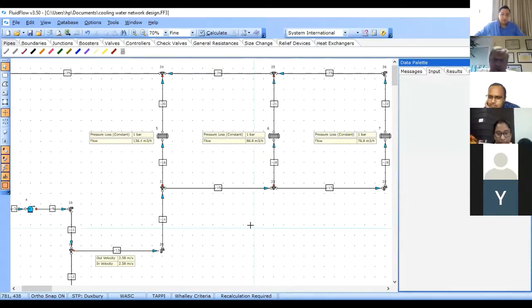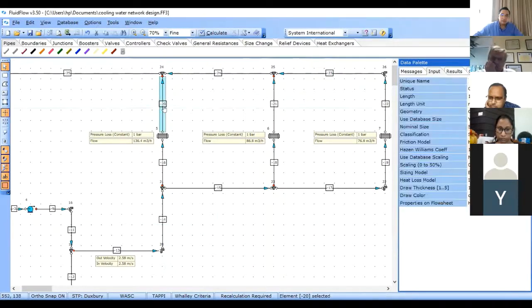Dr. Joseph, you are saying something? Yes. Thirty years ago, in a problem like that, we used restriction orifice. Because the people in the plant don't have time to adjust the ball valve. So we decided to put restriction orifice. So that is, instead of any flow control valve or manual globe valve, these three lines could have restriction orifice, right? So we'll simulate that.